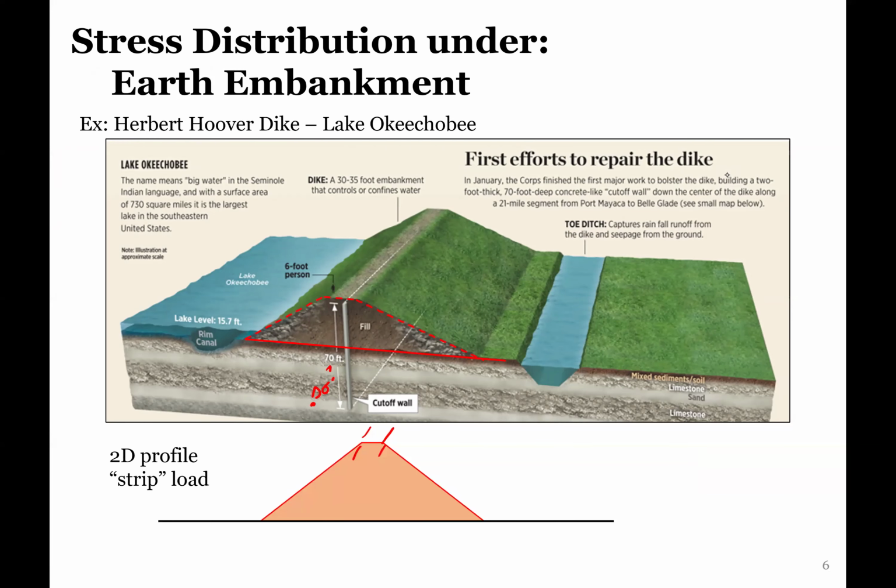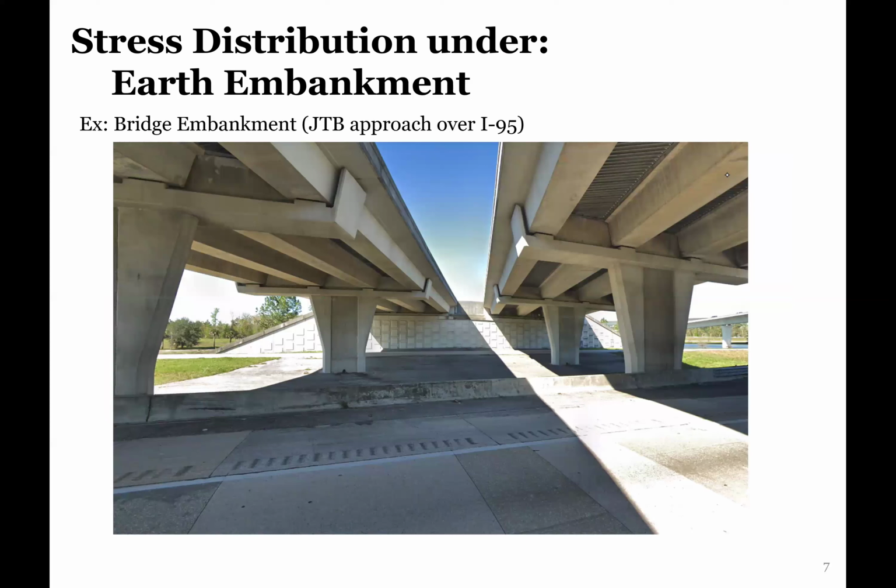And the increase in vertical loading underneath this would be something that we would need to consider. Now, we also see this in terms of embankments coming up to a bridge approach. You can kind of outline and see this here. If this is our soil layer here, we see this again, a trapezoidal increase of soil height. That is going to cause some type of increase of stress.